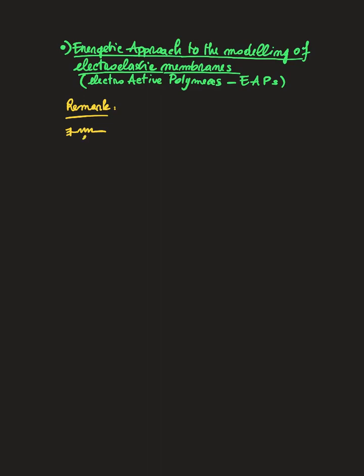So if I have a spring with an elastic constant K, and the spring is under the action of a force F, then to find the elongation of the spring, which I call x, I simply have to compute the minimum of the total potential energy U, which is equal to 1/2 K x squared minus the work of the force F times the displacement x, okay?